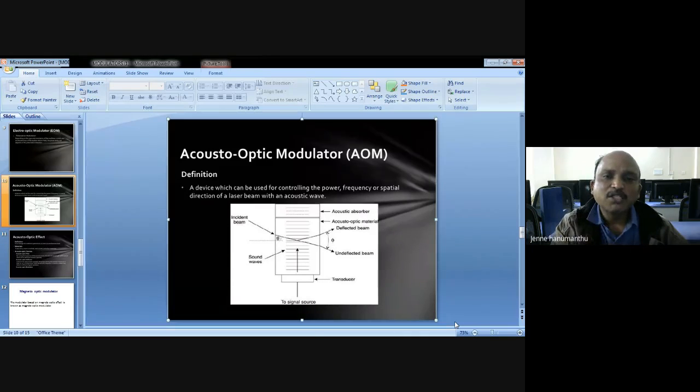Here also, in the acousto-optic modulator, AOM, the word acousto refers to sound. With this sound signal as our control signal, we can change the refractive index of the medium such that we can change laser beam characteristics, like phase, polarization, frequency, amplitude. Any of the parameters you can change by using an acousto control signal. Clear my point?